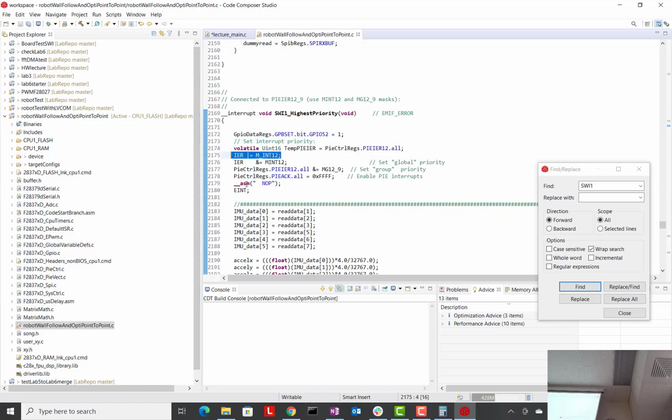And then finally, the last most important thing is when you come into this highest priority software interrupt, it re-enables interrupts right here. Okay? So what that means, and by all these other assignments here, this is allowing certain interrupts to interrupt this function. So this is a function that's interruptible by any interrupt of higher priority.